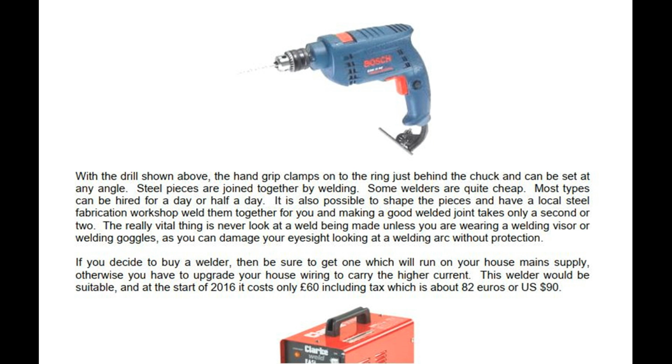The really vital thing is never look at a weld being made unless you are wearing a welding visor or welding goggles, as you can damage your eyesight looking at a welding arc without protection. If you decide to buy a welder, then be sure to get one which will run on your house mains supply, otherwise you have to upgrade your house wiring to carry the higher current.